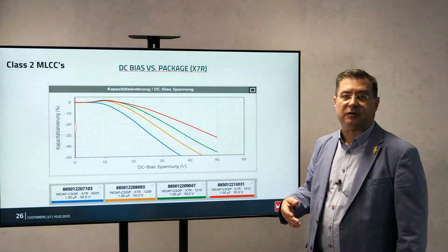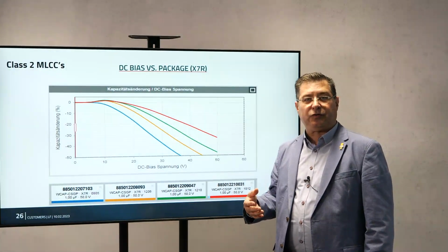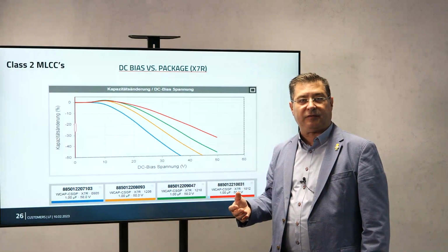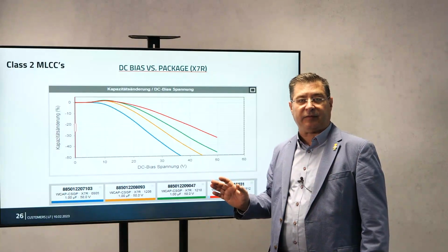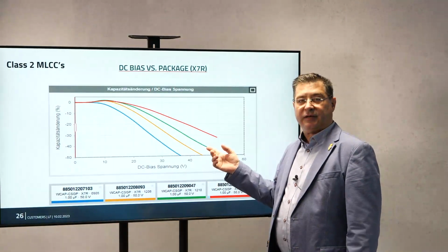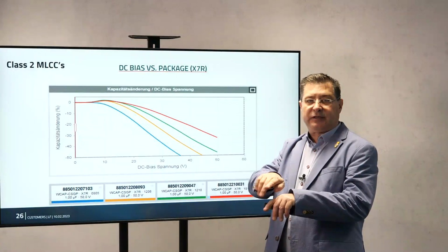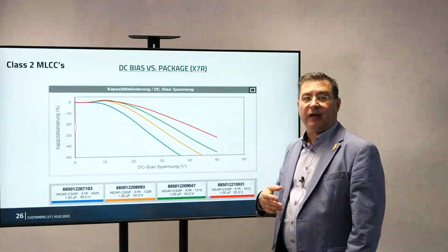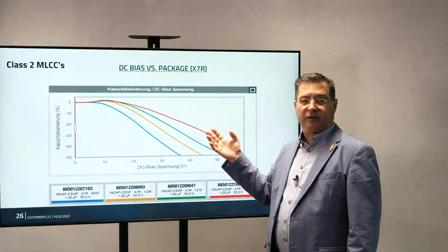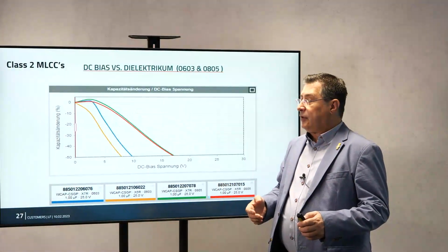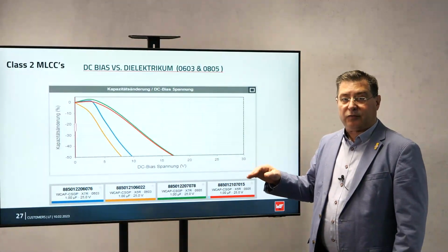So that is the reason why we don't say you should use a 0201 capacitor, because in the datasheet everything looks the same, very nice. But in reality, of course, if you have just a few plates or two big plates, like an 1812, it's a big difference in DC bias load. It looks much dirtier if you go down to smaller components.